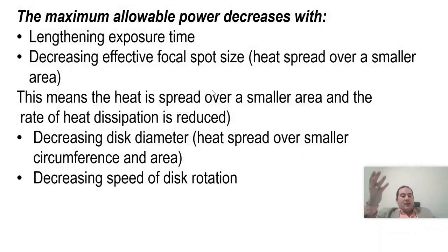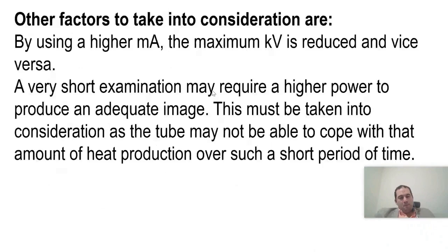So, did you increase the heat generated on the anode or not? If you reduced the maximum power output of the system, then that's the significant change you have made. This is the point I was telling you about. If you use milliampere, you won't be able to use the maximum kV with both milliampere together. So you have to increase one and decrease the other to reach the ideal that the machine can give you